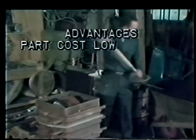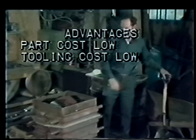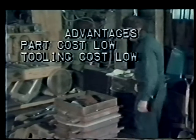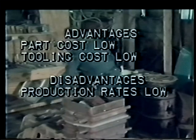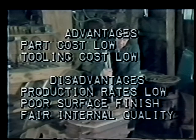In sand casting, part cost is low, and tooling cost is low. But since a new mold must be produced each time, production rates are also low. Also, the sand mold provides a poor surface finish and only fair internal quality.